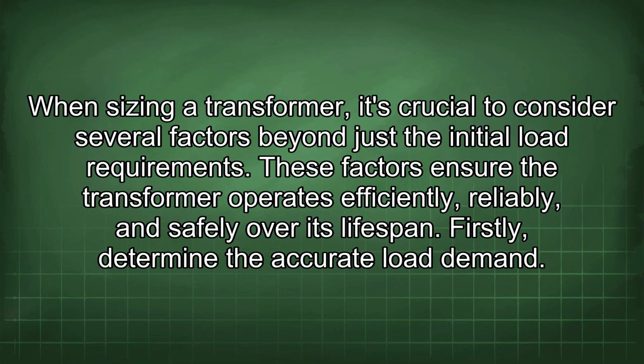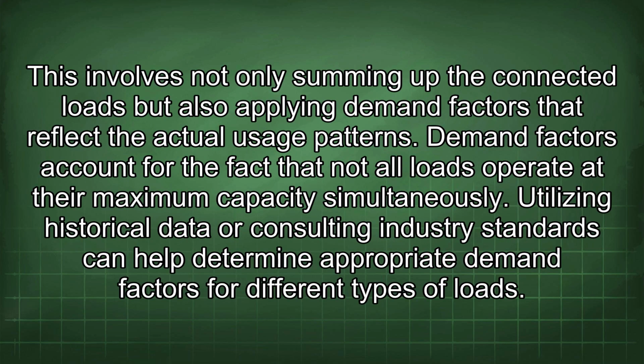When sizing a transformer, it's crucial to consider several factors beyond just the initial load requirements. These factors ensure the transformer operates efficiently, reliably, and safely over its lifespan. Firstly, determine the accurate load demand. This involves not only summing up the connected loads but also applying demand factors that reflect the actual usage patterns. Demand factors account for the fact that not all loads operate at their maximum capacity simultaneously. Utilizing historical data or consulting industry standards can help determine appropriate demand factors for different types of loads.